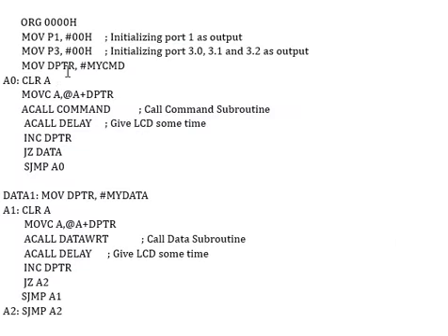So let us start with the command first, because without sending the command you can't initialize what you want to display over there. MOV DPTR, #mycmd. This indicates that whatever mycmd location content is there, that content you are going to move to the DPTR, meaning from that particular address whatever commands are there, that will be stored. And that is done in this way.